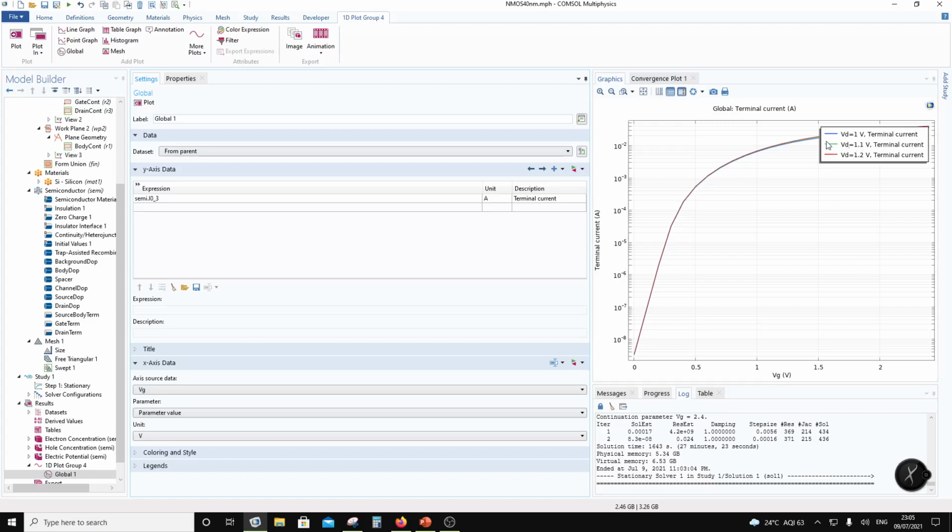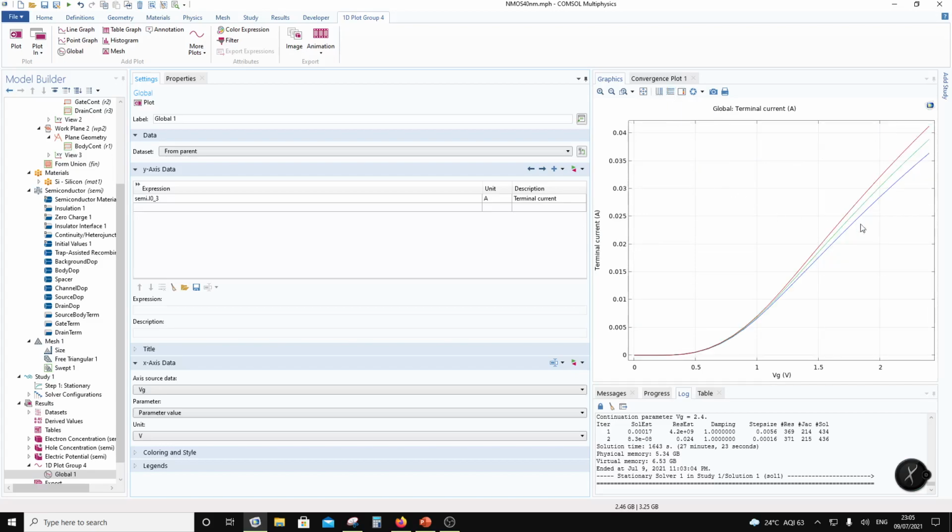And after that, let's move this legend so you can switch off this by this. After that, what you see over here is a mobility degradation. So let's put it again into linear scale. So you see that the slope is going up, and ideally it should go up as a square, but then it becomes linear, and then it becomes less than linear, right? So basically it's going to just fall off, right?